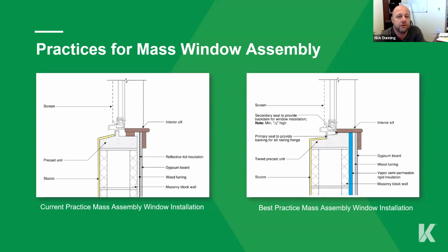And then you have waterproofing on your plaza decks, things like that. That's going to be more of a 20-year system. Those can be hot applied, obviously a lot more expensive, but they are what you're going to want to use when you're dealing with more than a typical balcony, walkway, things of that nature. So really maintenance is the key, but there's nothing out there urethane based that really lasts more than 10 years in reality.